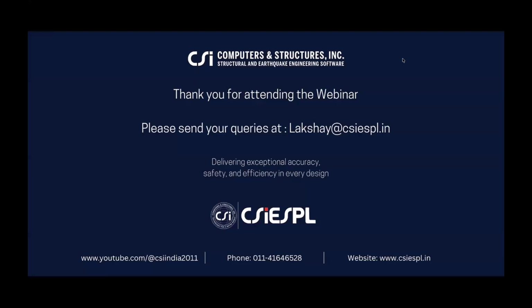For floating columns, the same procedure can be applied, but there you will be reducing their stiffnesses or releasing their end moments. We will discuss it in another session on floating columns, but the same concept remains applicable for that too. Yeah, 2 times the DBE is equal to the MCE, you can say. That is explained in step number 3 of the slide, in our recommendation slide.